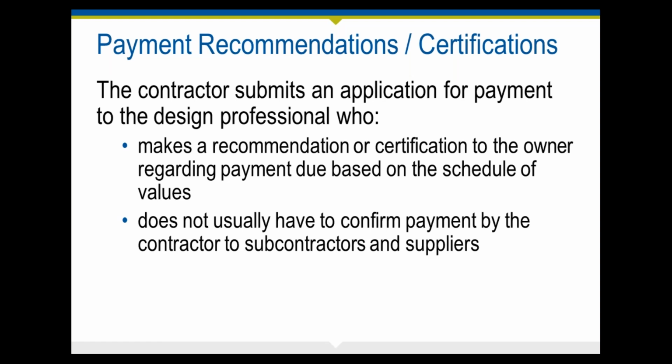So typically, the recommendation is that you call them record drawings so that it is clear that you are providing this information to the owner based on information records that have been provided to you by the contractor as to the location of pipes, walls, and so on. You're not certifying that it is the actual location, but they are drawings that you've provided to the owner as record drawings so that they have a set that reflects where you think the construction occurred. So generally speaking, that is what you need to be thinking about for your construction phase responsibilities.